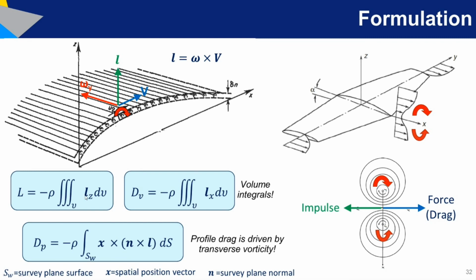But the far field method didn't relate profile drag to vorticity. Now it's clear that the impulse linked to the velocity deficit also generates profile drag. So we can profit from different aerodynamic analysis methods to improve our understanding of the physics.